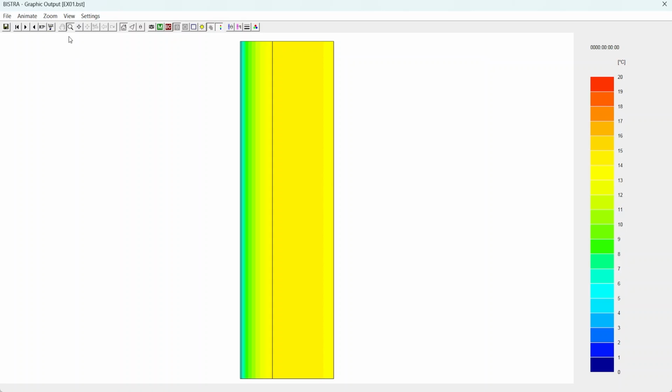We can make an animation from the results of each time step using Make Movie, but a word of caution, it might take a lot of processing power for complex geometries to load results for each node for each time step. Therefore, it's better to save the images for the calculation results and make an animation video externally.